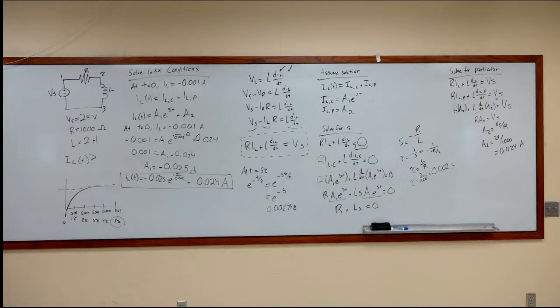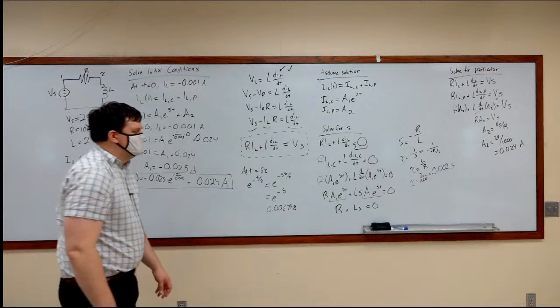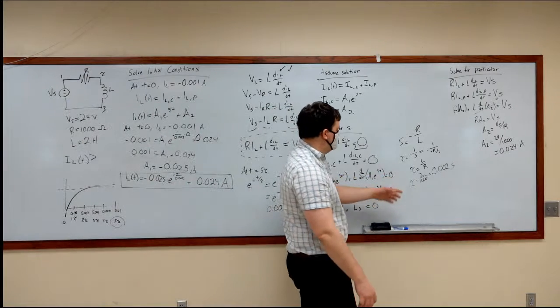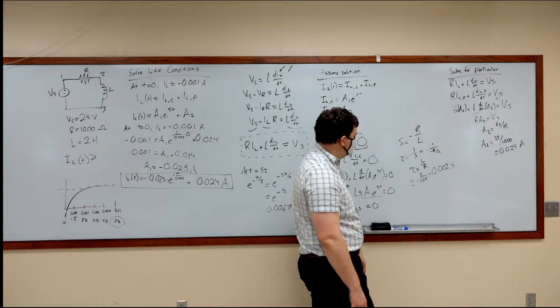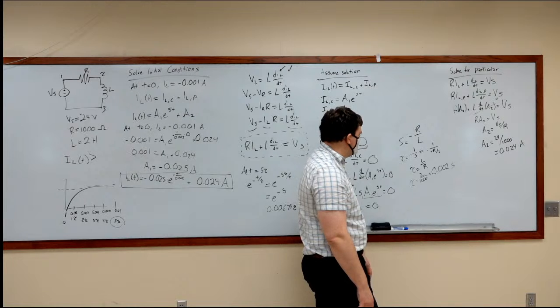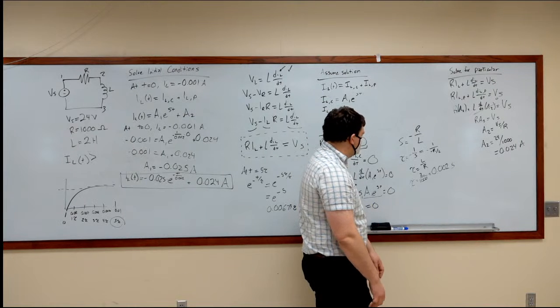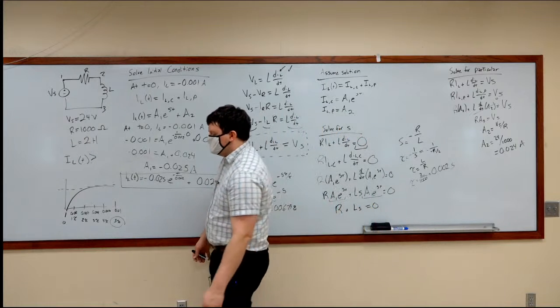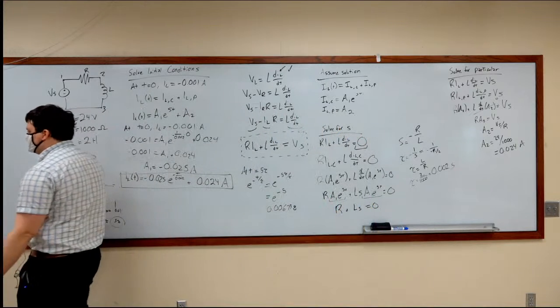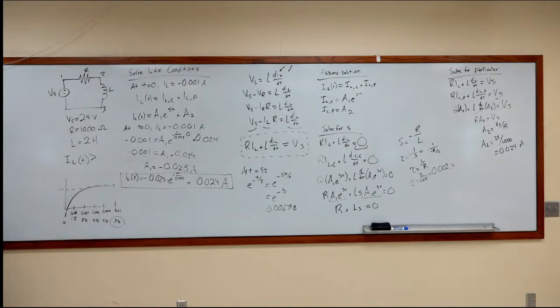Okay? So increasing resistance will make this take a shorter amount of time. My bad. Exactly opposite. It's true for capacitance. Here, if you decrease the resistance, it actually reaches steady state faster because tau becomes smaller.